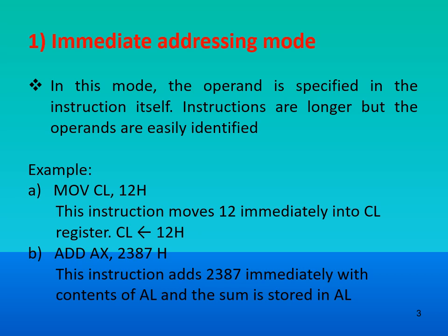So second example, ADD AX, 2387H. This instruction will add the value 2387H immediately with the contents of AX and the sum will be stored in AX. So here also the source operand is 2387H, which is immediately available, and that's why the name immediate addressing mode.